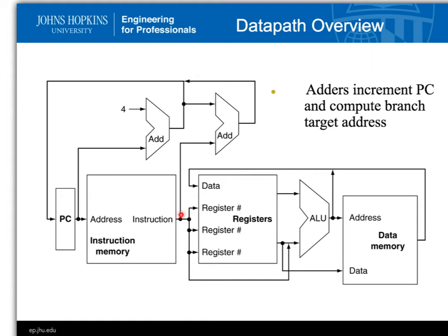We'll talk about what this is, but it's actually what's going to happen if this is a branch or a jump. The information will get sent up here, and a different program counter will get calculated, but that'll become more clear as this lecture goes on. Anyway, the 32 bits get sent here, and remember we have those fields with register numbers in them.